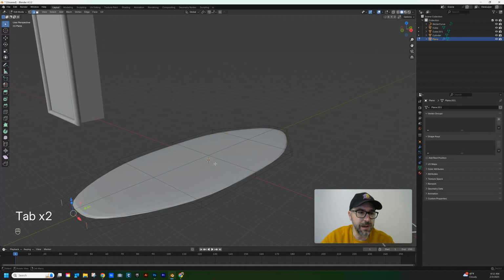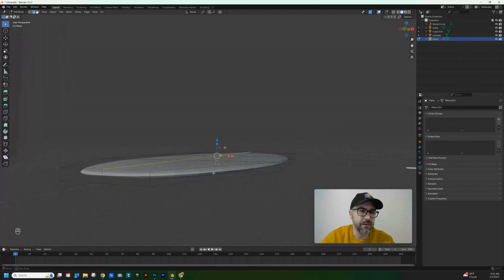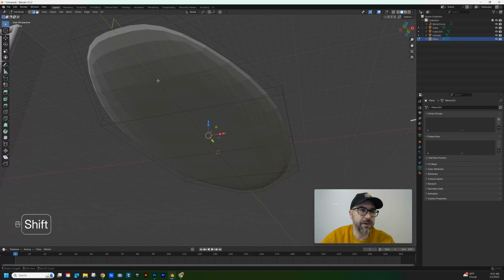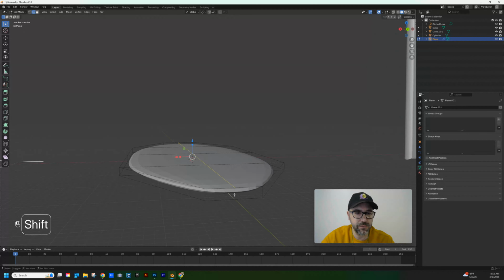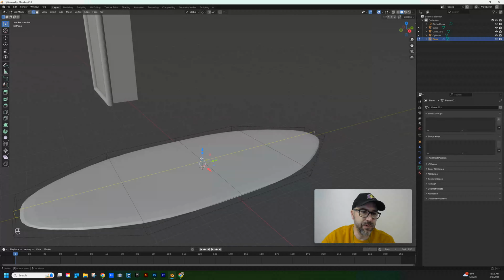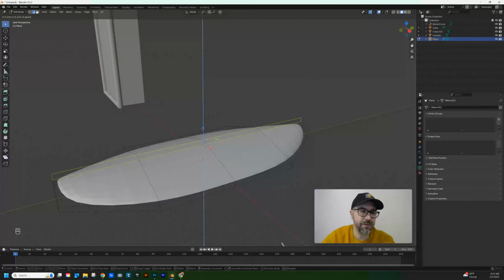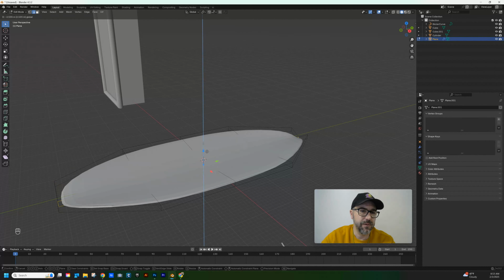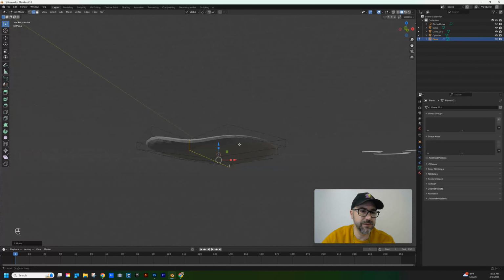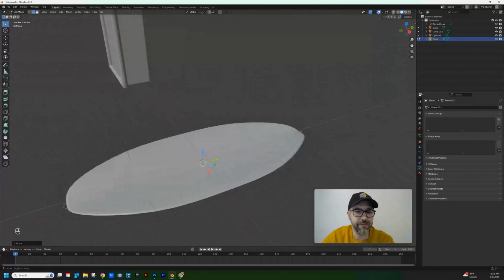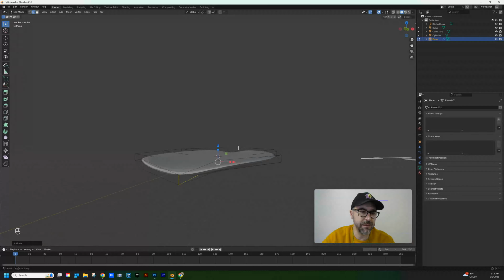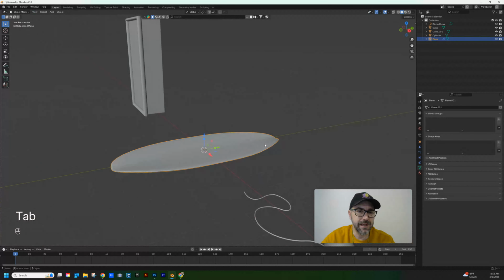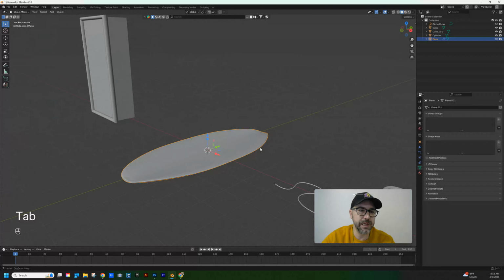Okay. If I select the cut that I made down the middle, so let's go to Edge Select, number 2. I'm going to grab all of these by rotating around it and selecting all those edges. There we go. And I can pull on this either up or down to give it some curve. Okay, so if I push it down, I've created this little dip. This is starting to look like a palm tree leaf. Or again, it could be like a fan blade if you want to do that. And that gives me this really cool organic shape.